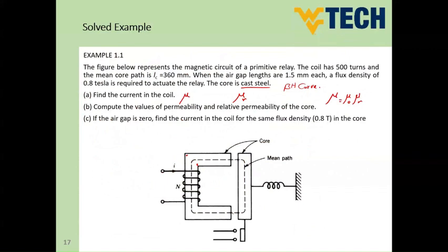So in industry, guys, we refer to the relay positions as open or closed. So this is called normally open relay. Once you energize this relay, this relay will be closed. So we say this is a normally open relay.